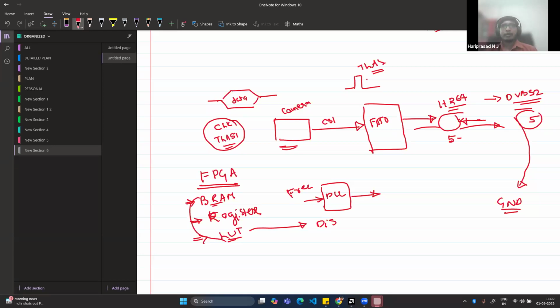But given one FPGA, I have limited memory, right? Now we talk about video processing or high speed processing or LLMs, but whatever memory is available inside the FPGA, like block RAM, registers, lookup table, that may not be sufficient. Let me show you exactly how much memory is available. I'll give you an idea of how the resource table looks when you choose one FPGA. Yesterday I was telling you to look into the 7 series product guide, right? So let me open that PDF itself.